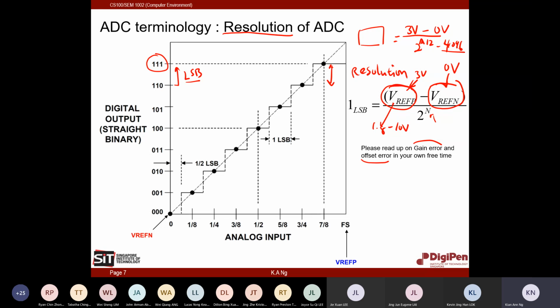Resolution is the first thing that you need to look for. For our lab 7, the microcontroller is 12 bits. Some systems give you 10 bits only. When you shop for microcontrollers, they can tell you, I have a 12-bit ADC. It does not mean the resolution is 4096. Depending on the manufacturer, some of the bits inside the range have errors.